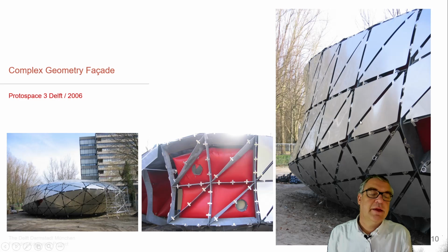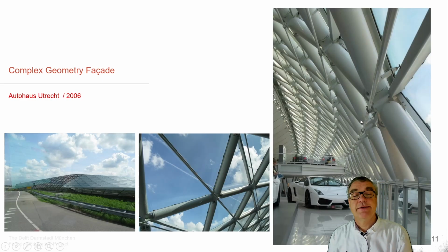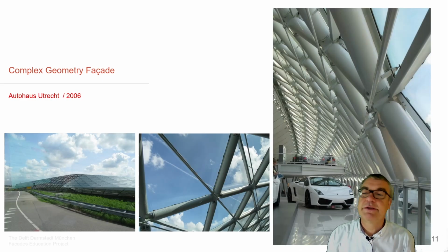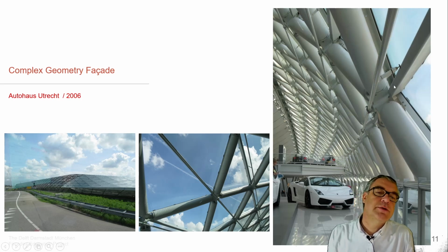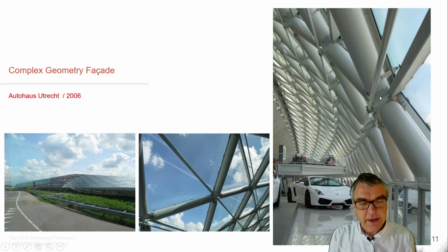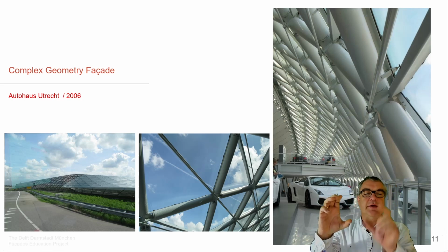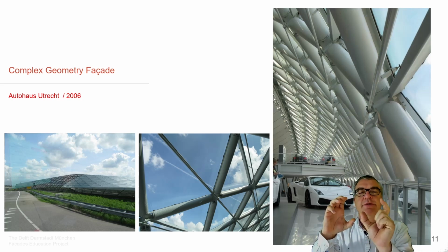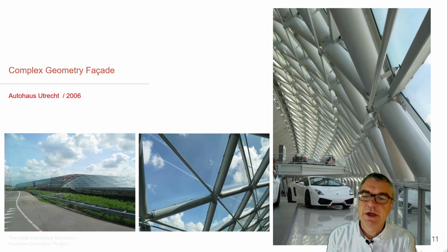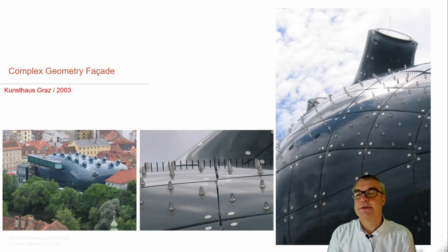It's rather experimental in this setup, but the same architect managed to do a lot more advanced project in Utrecht, an outer house where you see there's a main structure and a freeform shell structure, which has an additional layer of glass support structure, so a glass frame system, which is added on top of this shell structure. So there's a main structure, and then there's a glass system, a frame system, actually kind of a stick system, which is on top of this system, which then keeps the glass in position as a setup. How it is done here.